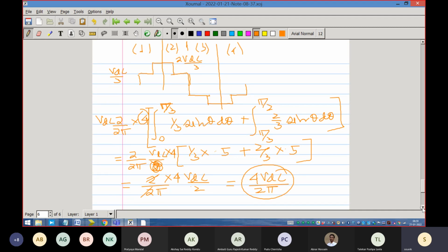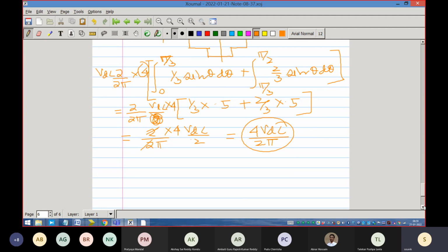You will see that which is expected, that the fundamental component is not changed because this is from one neutral to another neutral, and the difference between them only should be in the third harmonic component. So all other harmonic components should be identical. So there is no need to recalculate everything. Only we should check that the third harmonic component,